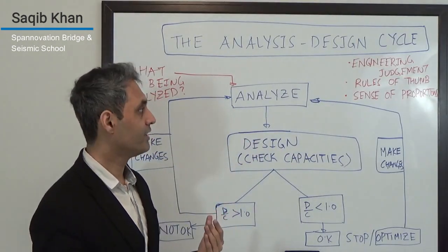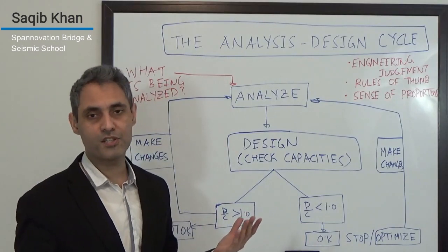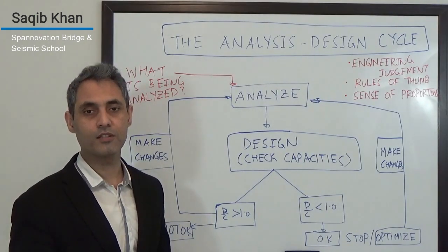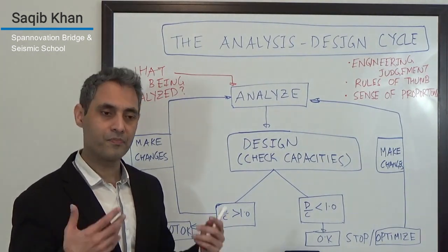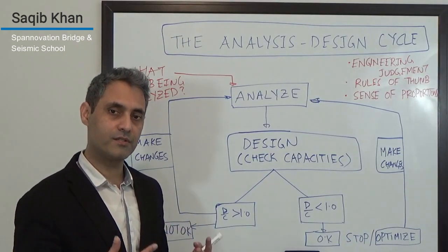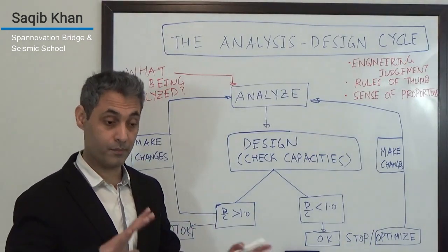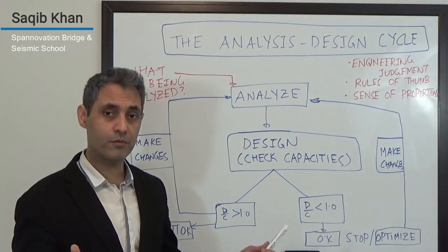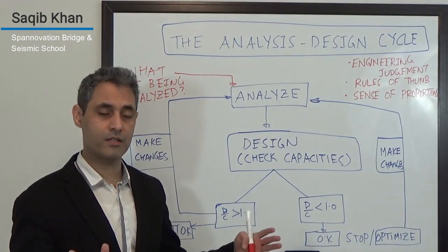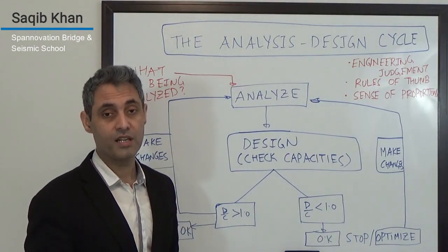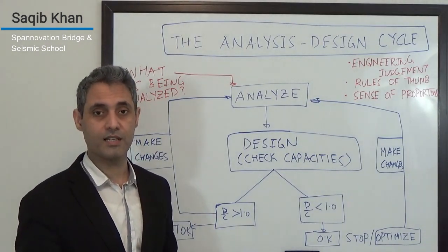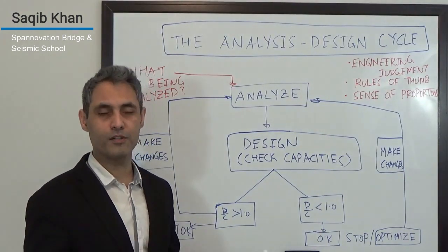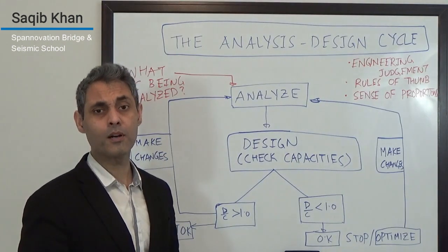I remember when I was in the first couple of years, I was looking at a bit of a complicated problem. This was a rail crossing in some marshland, so the design was basically to drive steel pipe piles and then put a thick 600 or 700 mil thick slab on it for rail loading. And the geometry was really governing in that case, so the skew on the slab was about 60 degrees. I did different analyses and grillage analyses, ran my loads and looked at different combinations of the moment this way and that way and torsional moments and combined them. It took me about a month.